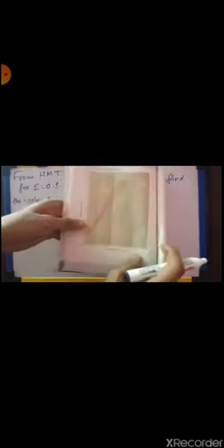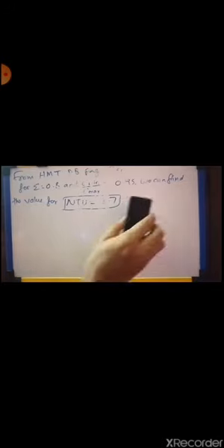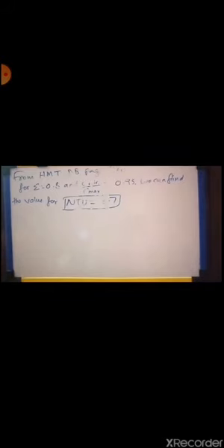From this data book graph, the y-axis gives the epsilon value, and the curves are C minimum by C max. For 0.8 and the curve 0.95, you get the value for NTU as 3.7. Okay. This is the technique. From the graph itself you can easily find out the value for NTU. No other extra calculations are required to find out NTU.